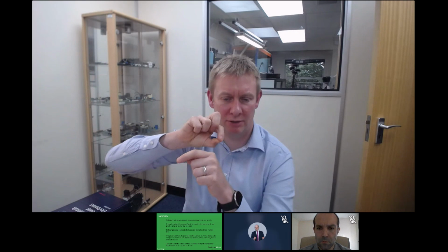Yeah, okay. So for active power factor correction, there are a number of topologies. And actually if you join our webinar on Thursday, we're going to go into some of those in quite some detail. For single phase systems, you tend to have a bridge rectifier, and then essentially following that is a boost converter, which steps your full wave rectified mains up to about 400 volts, but it pulls a sinusoidal current which completely tracks your input voltage. So that gives you unity power factor. For three-phase systems, it's done slightly differently, and we'll be talking about those on Thursday as well.